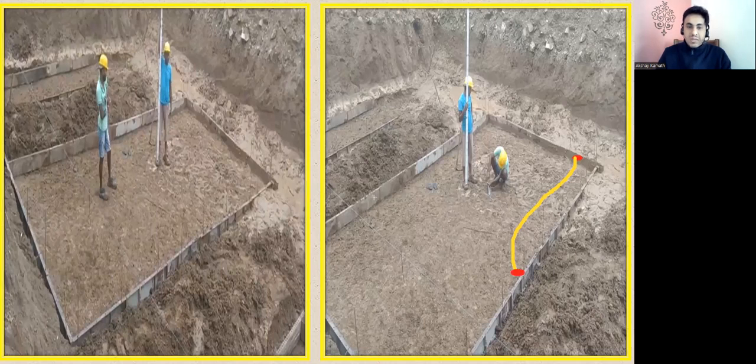Now again, let us say I want to transfer the level here. Again, I'll hold one end of the tube here, bring the other end somewhere here, and stop it. Once I stop it, the water will go up and down, and at one particular point it's going to stop. The place where it stops will be my 75 mm marking. Let us consider it has stopped somewhere here, and that itself is the level of the PCC. In this way, throughout the formwork, we transfer the level so that we get a uniform surface, right?